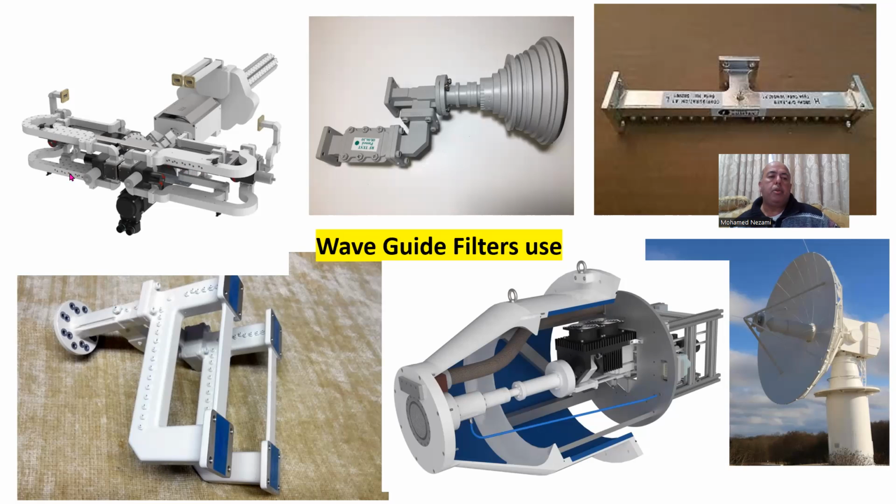All of these with these tunable screws are filters, as you can see here in the front. Same thing in here. This is a diplexer, same as this one too. This combines two channels. So here is a filter and here is a filter, and this is a common port. So this can be either diplexing or multiplexing, same as what's done in here.